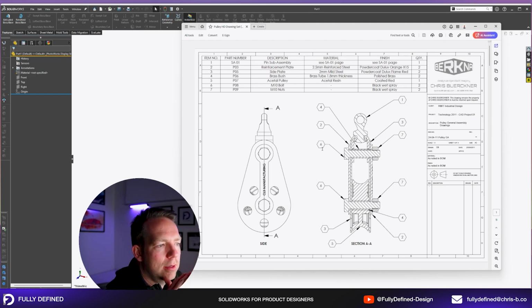Another key thing I'm looking for is if there's an element or an OEM part that is sitting in a certain position, okay, that may be the reference. So a cavity to fit that product, that part may sit in that position, and we reference around that, or we've got something with a hole in it, or something that rotates around. So with the pulley here, quite an obvious one to start with is either the lower pulley point, okay, that being your origin, or something to do with the form bracket and the pivot pin up the top.